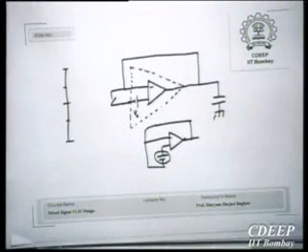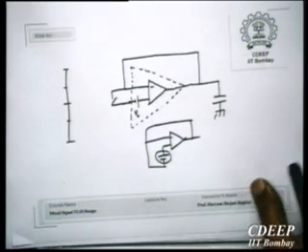In fact, that is the next thing. When I compare the offset correction at input and output, that thing will come. So right now, we have assumed that the unity gain is ideal. But eventually my real op amp will not have infinite gain. So what I will store here is in fact approximating the offset voltage, but it is not quite the output voltage. Okay, this is one possibility. Roughly this is what has been suggested for the offset correction. This is called input offset correction. So this stored voltage must then be subtracted from the input which is coming.